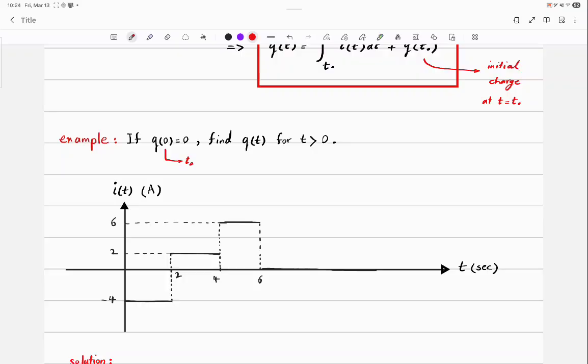Okay, what's the direction of the current? A circuit is given to us, and we want to analyze the circuit. This is what we do in this quarter. How can we know what direction of current we should apply to the circuit? From the positive voltage source to the negative? But if it is not a voltage source, if it's a very big circuit, some resistor in the middle of the circuit, how do you know which direction current is passing? You don't need to know. You just assume one direction.